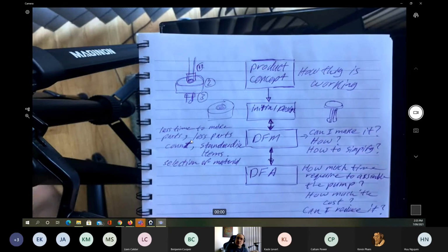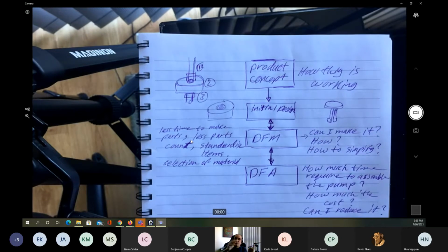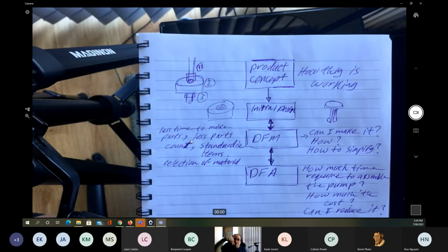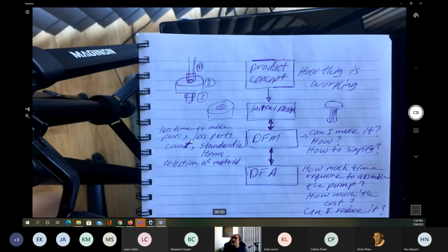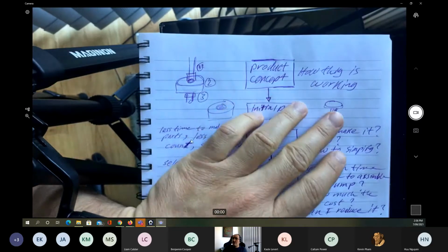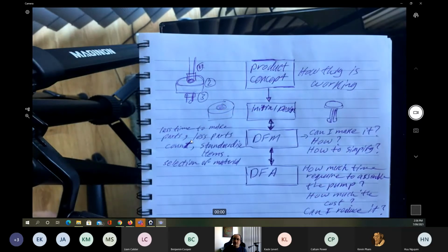So when you push it inside the hole, it will be closed, then it's going to open and fit. We call it snap fit. So you just need to push it instead of using the screw and trying to twist the thing. We can use this one to fit the washer over the foot valve at the bottom. Now we saved more time on something else.